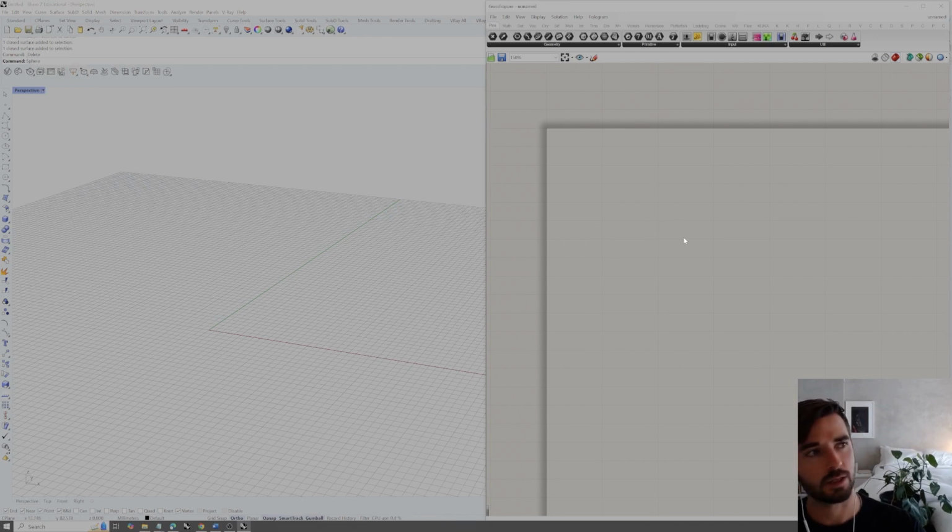In Grasshopper, we can double click on our canvas and begin typing whatever that command may be. In this case, if we want to construct a sphere, we can type sphere. There's an option it's suggesting, which is called sphere, and it has a small sphere icon to the left of it. If we hover over that, it gives us additional information saying create a spherical surface. If we click on that, it's going to instantiate or add a component, which is this little battery thing in our canvas.